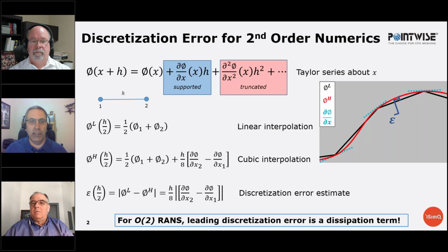But the idea is that we're going to examine the effect of going from the continuum realm of the Navier-Stokes equations into solution numerically on a mesh. And what happens there is we always impose, regardless of your solver, a known solution at a certain level. So for instance, if you look at a Taylor series expansion here, that's a perfect continuum expansion if you have an infinite series.